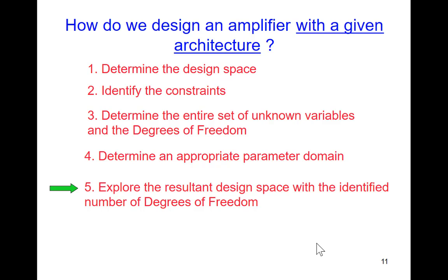Let's talk a little bit about exploring the design space. When we look at this two-dimensional design space, power and the excess bias, we can look at the characteristics that this op-amp has, the gain and the gain bandwidth product, throughout that design space.